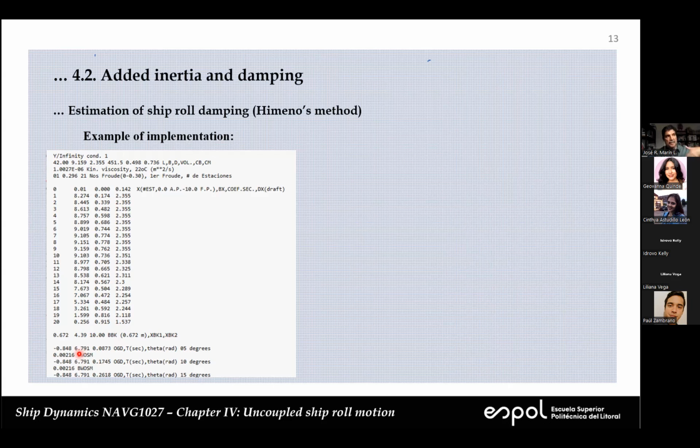Internally, there is a procedure to estimate the influence of the velocity. That's why you're given the Froude number. From there, they calculate the wave generation damping coefficient at a certain velocity, calculate all the other coefficients, add them up, and then integrate over the whole ship.